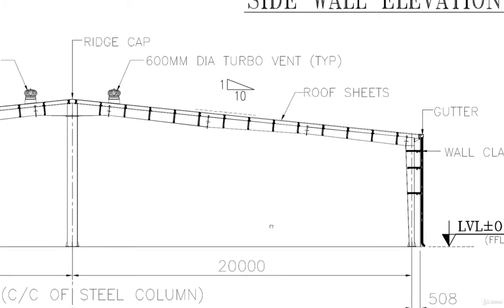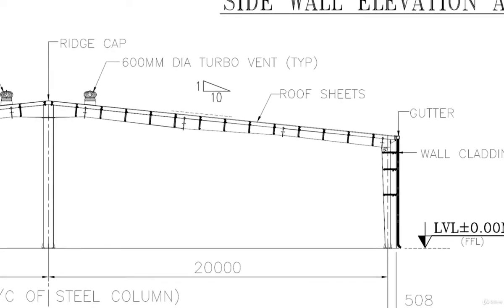So basically PEB sections are made up of built up sections. To save structural steel, we have an option to put steel only in the areas in which the bending moment or shear force is high. At the beam column junction, as this is a fixed end condition, a large amount of moment develops here.